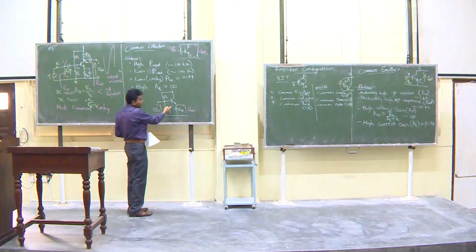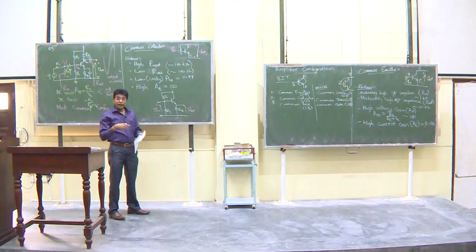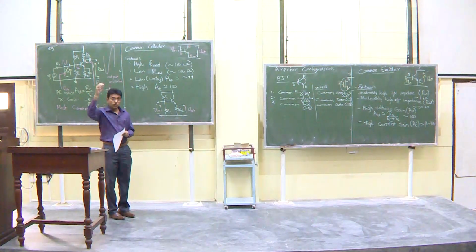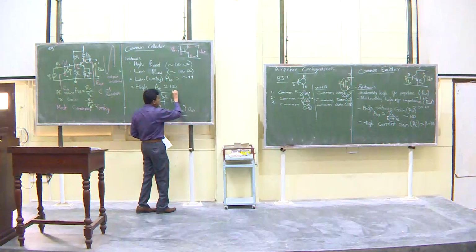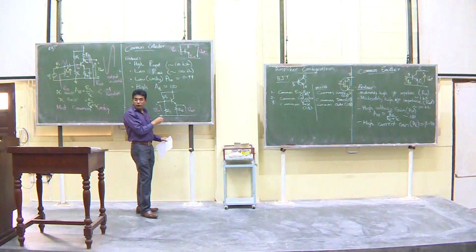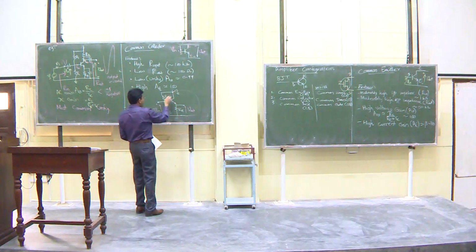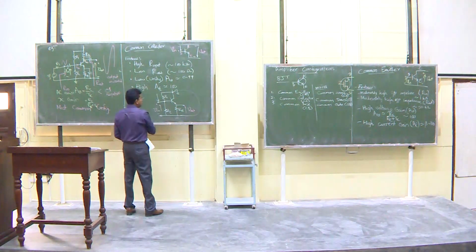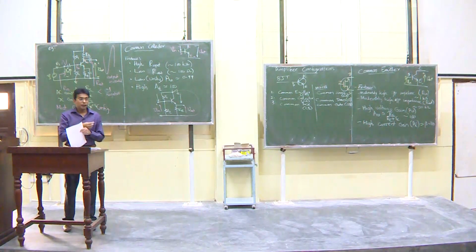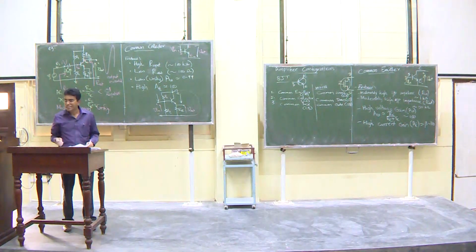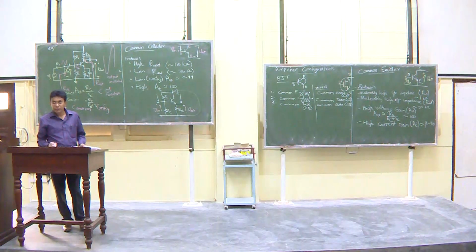Now, the reason why it does not look the same is because we have drawn the DC circuit. If you look at it as an AC circuit, the DC voltage sources are short circuited or replaced with their internal resistance, in which case this place is the same as that place. So, therefore, this is the same as ground. In that case my input is with respect to ground, and the output is the emitter. Now, it is the same, is it not? So for DC you do not see it, but for AC it is the case, okay, clear? Right.